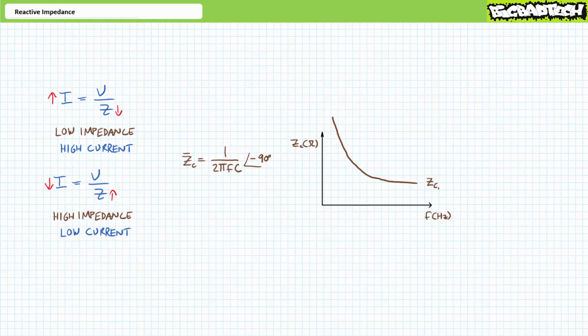Think about it. What's the steady state impedance level of a capacitor in a DC system? After the transient charge phase ends, a capacitor essentially appears like an open circuit, or an infinite impedance. After a capacitor is fully charged or fully discharged, current flow ceases. The complete halt of current flow perfectly defines a high impedance element.